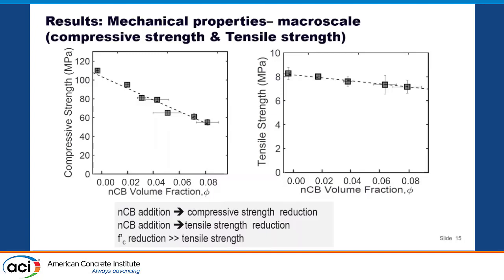Second thing, you have given a good reason for the decoupling between the compressive strength and the toughness values, because toughness is increasing while compressive strength is decreasing, which is surprising. My take on that is because of the crack deflection. My take is two things. One is you can control the fiber orientation by controlling the rheology of the paste. I'm guessing that it is because of the orientation of steel fibers. Yes, that is one point.